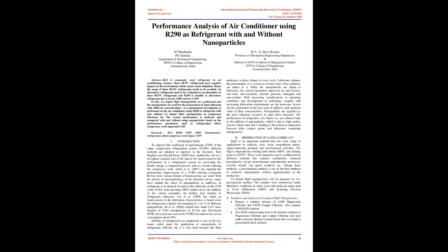The performance of composites, oils, fluids, etc. are enhanced due to the addition of nanoparticles, which is due to high surface area to volume ratio that is leading to the extensive interaction between tribo contact points and lubricants containing nanoparticles.